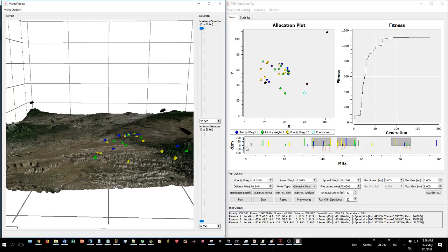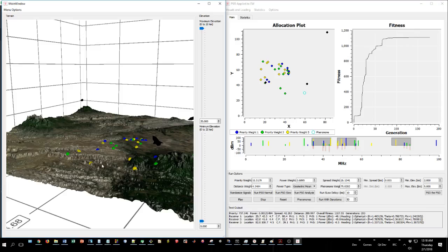And you can see here the blue, yellow, and green are respective to the transmitter signals, frequency, and power. Then the underside has a pink bar. That's a negative dBm. That's the receiving side. That's the power that the receiver is actually picking up.